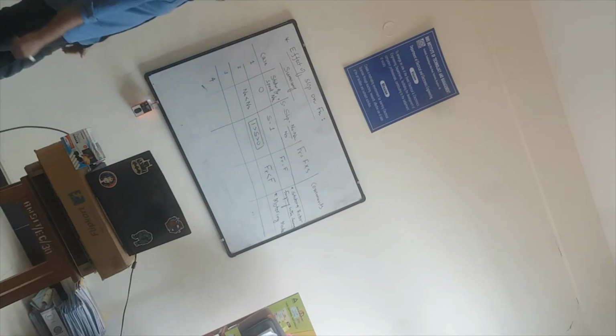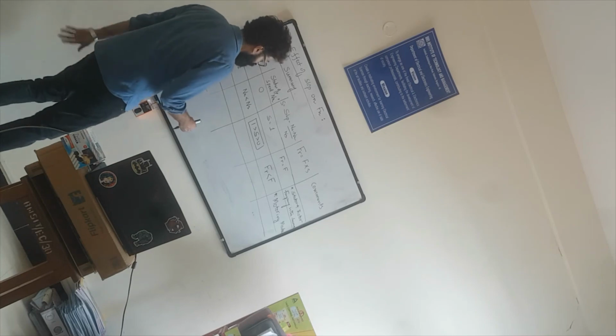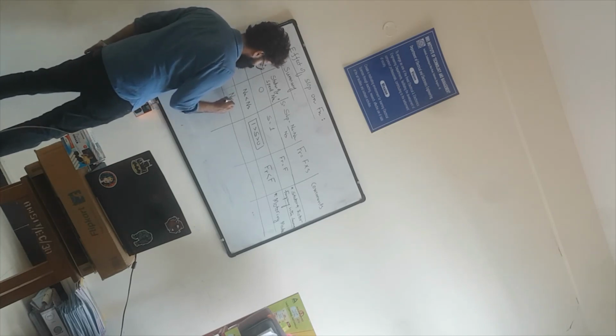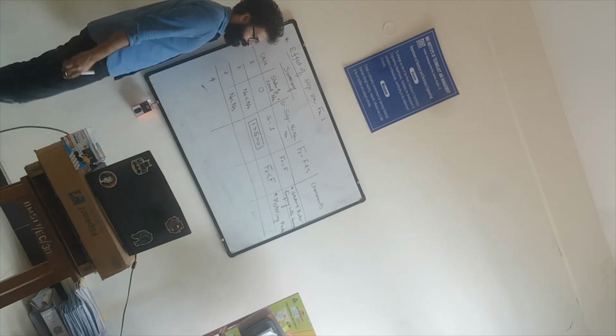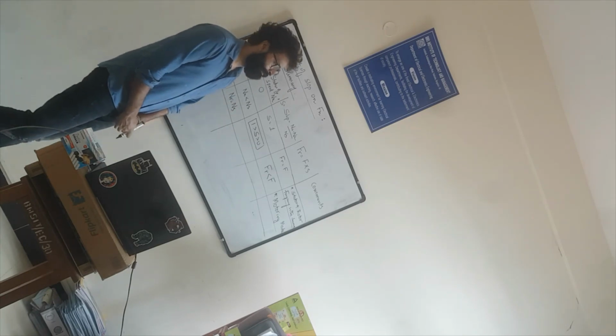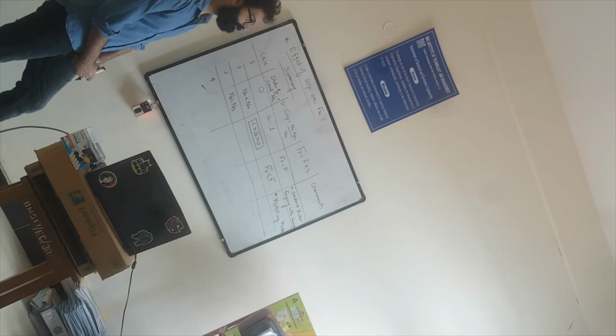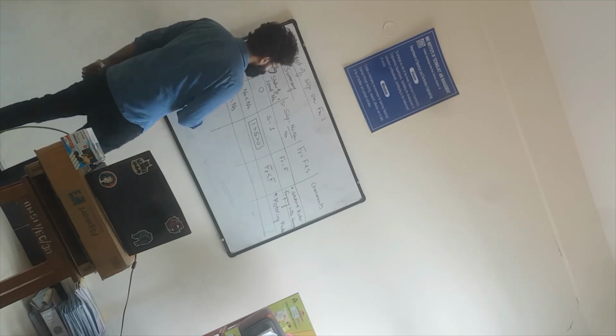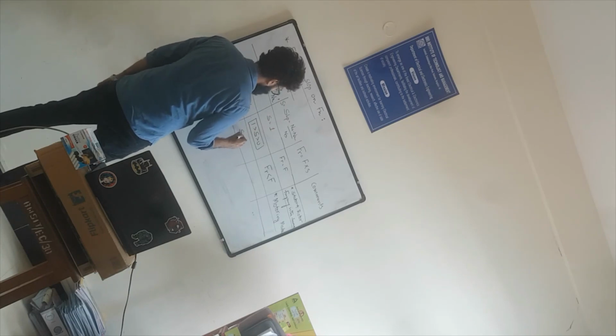Okay, alright. So third condition, crazy condition you could say, NR is equal to NS. What happens by chance, the rotor speed becomes equal to the stator speed. When NR is equal to NS, slip becomes 0, due to which Fr becomes 0.